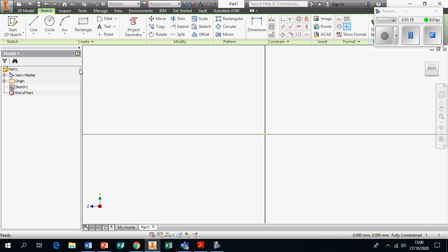So to design this Lego man's head, what we are going to do is we are going to click on the line command. So again, on the icon, left click. And we are going to bring our line command down to the origin. So that's where you see this yellow dot in the center here, and hover over until it snaps in place.